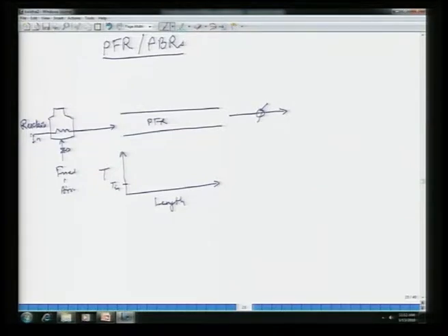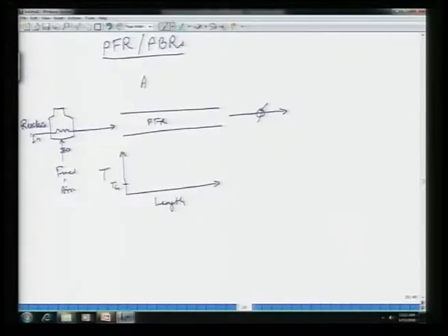So, imagine what is happening in a plug. Initially the plug is reactant rich. So, reaction happens. Because reaction happens, the heat of reaction gets released. It is an adiabatic plug flow reactor, that means it does not lose or gain any heat from the environment. If it is adiabatic, then all of that heat that is released in the plug goes to increase the temperature of that plug.